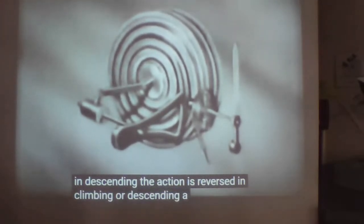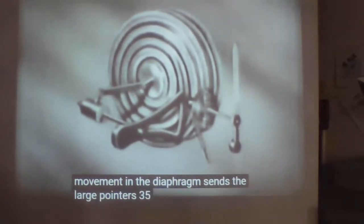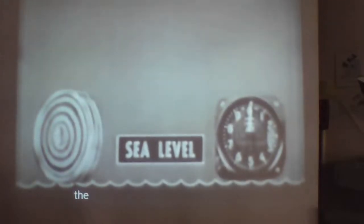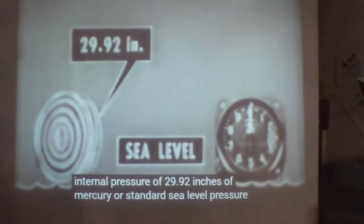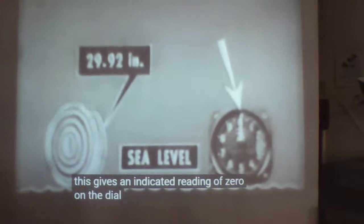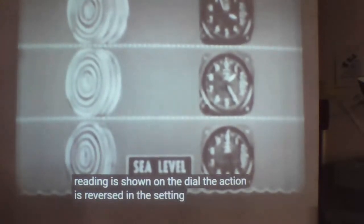In climbing or descending, a 1/4 inch movement in the diaphragm sends the large pointer 35 times around the dial. The diaphragm is sealed with a constant internal pressure of 29.92 inches of mercury, or standard sea level pressure. This gives an indicated reading of 0 on the dial. As the aircraft ascends, the decreased atmospheric pressure allows the diaphragm to expand, and a higher reading is shown on the dial. The action is reversed in descent.